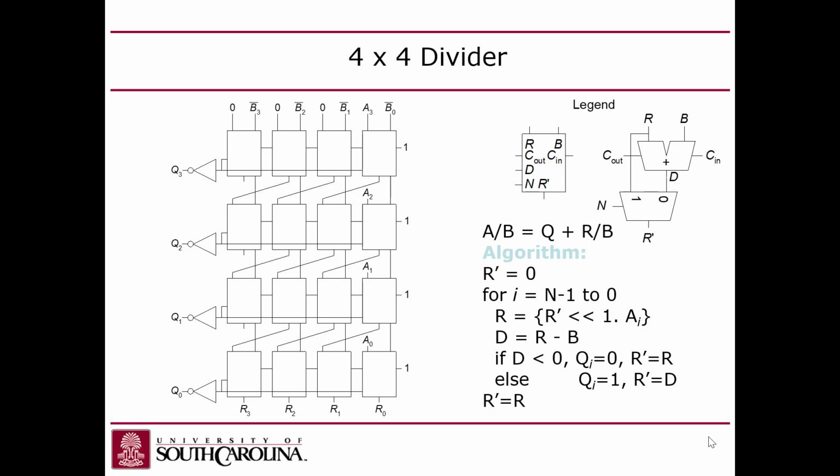If you do a subtract and the carryout is 0, then that means you got a negative number in the result. So if you complement that, this is saying that you're getting a non-negative result. That would mean that when you subtracted the divisor from the shifted dividend, you got a positive or 0. Does that make sense?